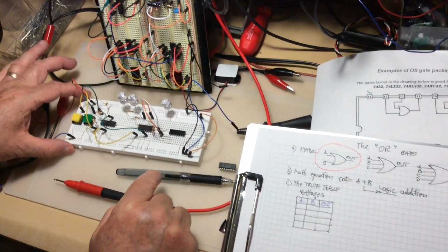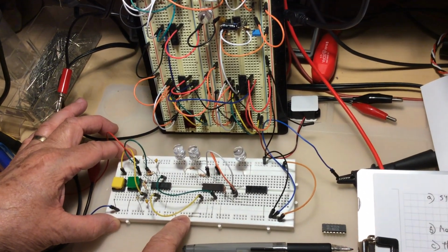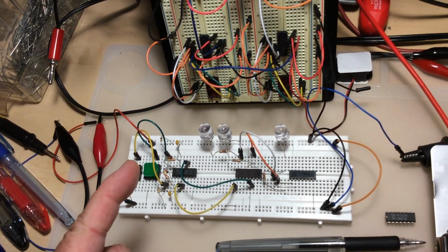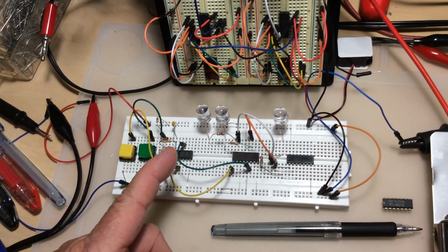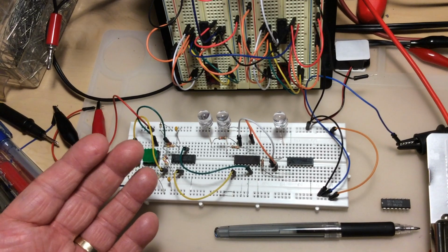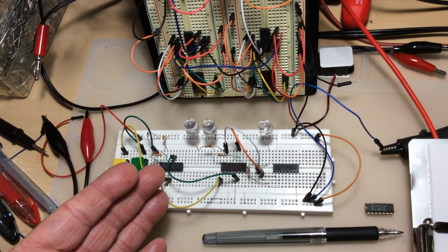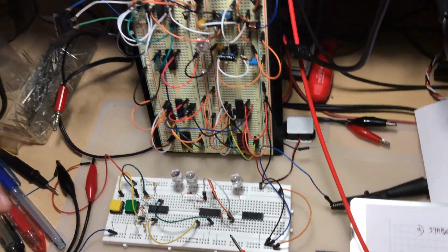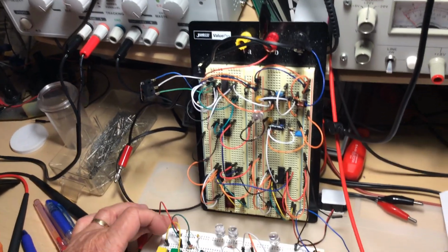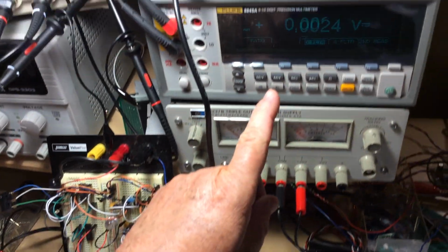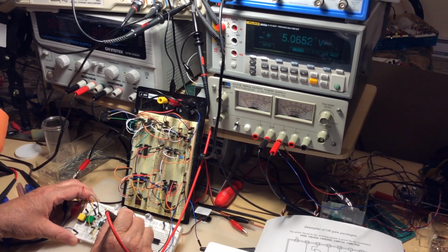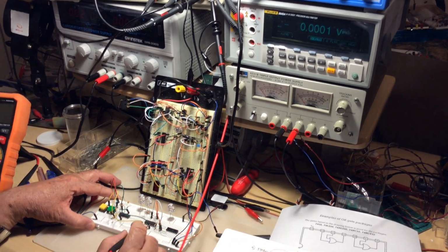So here, on this white breadboard, I prepared a little trainer for you guys. And according to one of our previous videos, when the light is off, that's equivalent to a 0 logic, or 0 volts. When the light is on, that's equivalent to a 1 logic. But we're going to measure voltages. At this moment the power is on already. How do I know the power is on? Because if I'm watching the multimeter here, and if I measure pin number 14, I measure 5 volts. So that's how I know my package is energized.